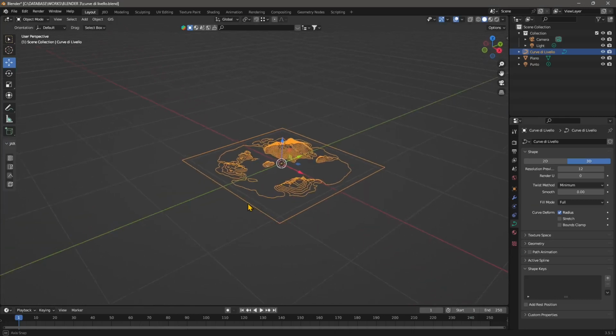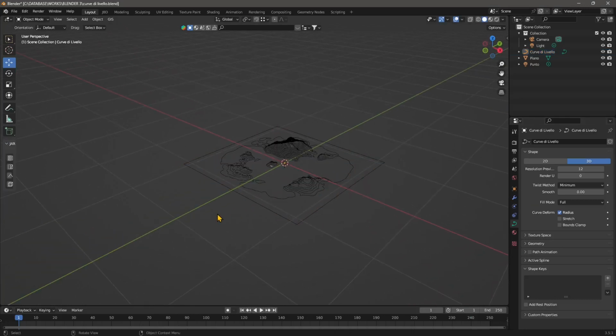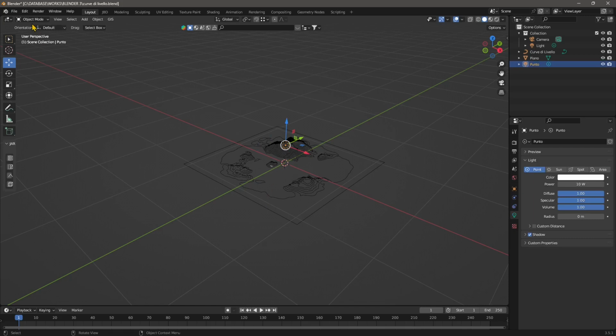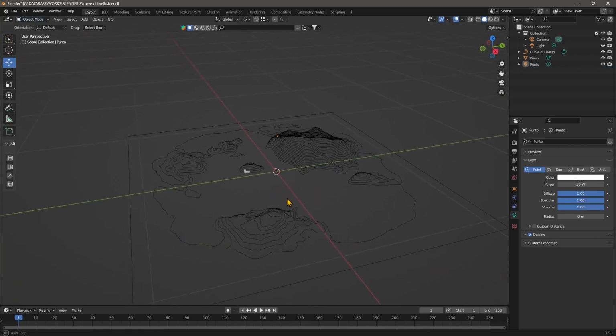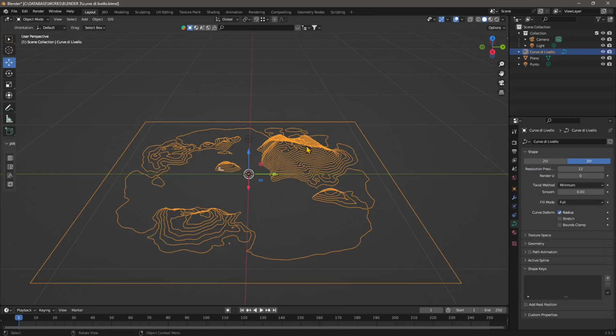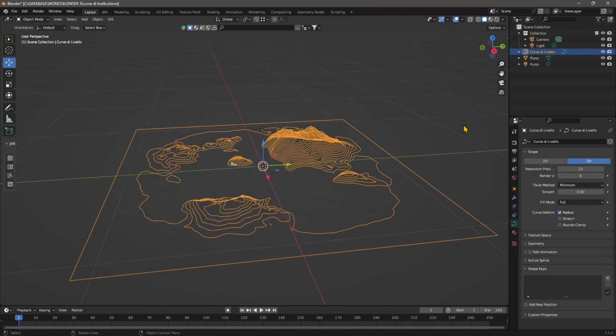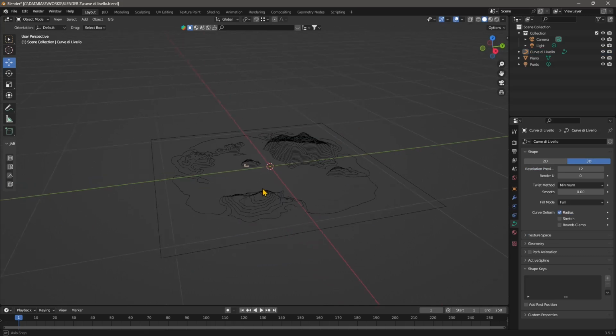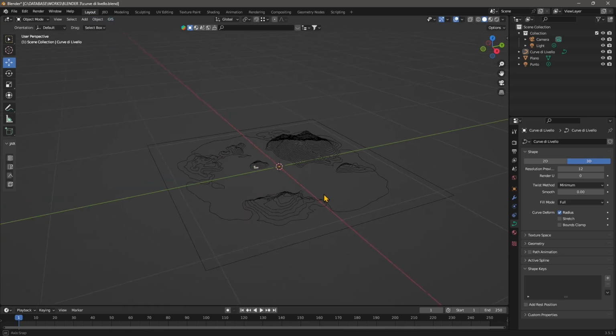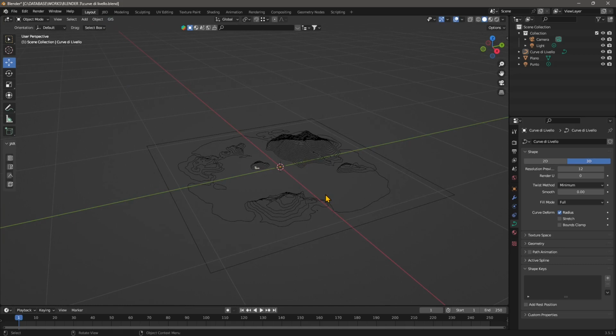In this quick video guide, we're going to see how we can generate meshes and also Nurbs surfaces starting from curves. So this is good if you want to do a terrain using level curves. And we also saw in another video how you can create curves, level curves, starting from a terrain or a landscape here in Blender. We also used the GIS add-on to create terrains from actual terrains using Google Maps and other geographic information systems.